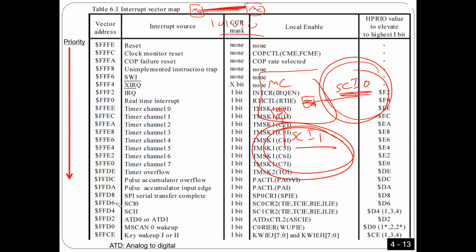So for the interrupt here, this is the number you have to use, as we did before. Again, you should understand why we need an interrupt here, guys. If I want to know whether I received the data or not, what should I do? Number one, you can do polling, which for sure is a waste of time, or you can just use an interrupt. Once the data is received, the serial communication is going to trigger an interrupt. And then inside the interrupt subroutine, you have to read the data.